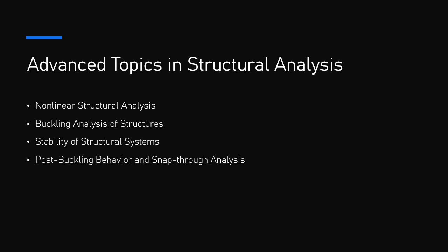4. Shell and membrane structures. Shell structures and membrane structures are often thin and flexible, making them prone to snap-through instability under load. Stability analysis involves modeling the large deformations of the structure and identifying any potential for collapse or instability due to lateral forces or thermal effects.